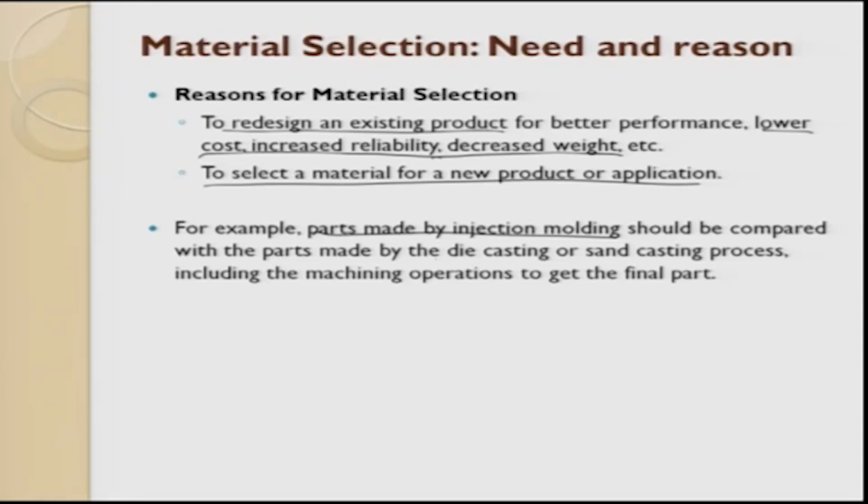So for example, if you have a wheel rim to be made, this can be made out of three choices. One is casting process, it can be made by die casting process, or today they are looking at injection molding process. In injection molding, polymer is used, and the carbon fibers, I said, can exist in several forms. So they try to make a three-dimensional reinforcement and inject polymer into it, and they are also thinking of placing a location for inserts. So this is what it is.